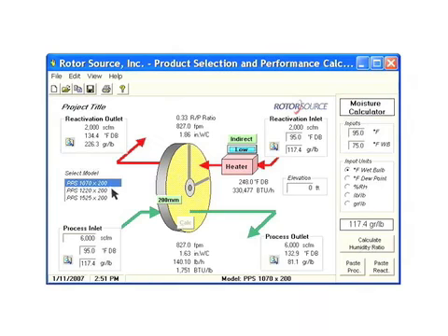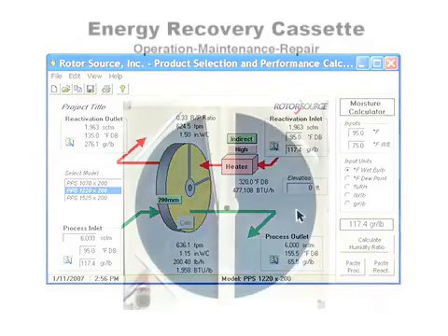You can also look at the next larger size wheel, as with the energy recovery program, to then look at the different effects. In the event that a user is using a direct-fired natural gas furnace, use of the indirect button will add the moisture created by combustion such that it is represented in the exhaust air. Again, this program selects different models which are then used with our drawings and our data sheets to give the best representation of submittal for selection, and both programs include an elevation input for different heights of elevation.